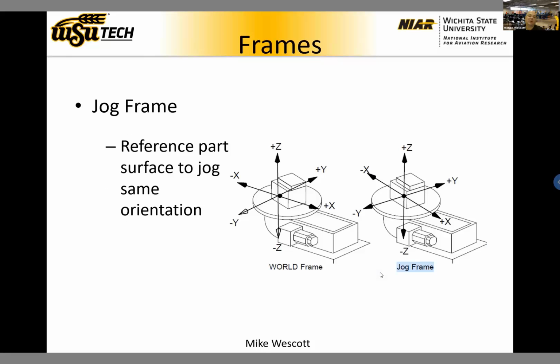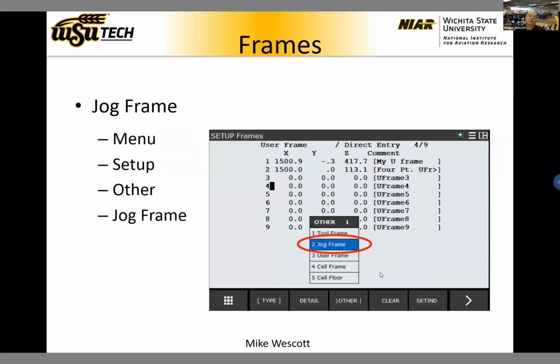You can set them up with any orientation and location. To get to jog frames, again, you go menu, setup, frames, other than jog frame.